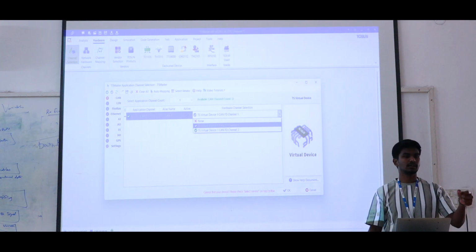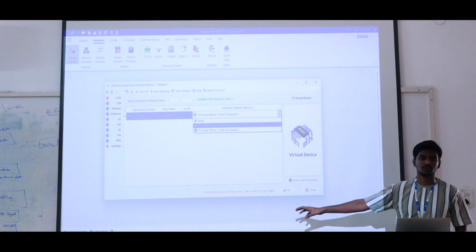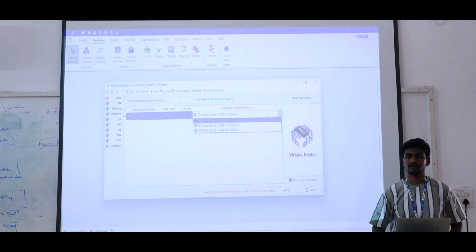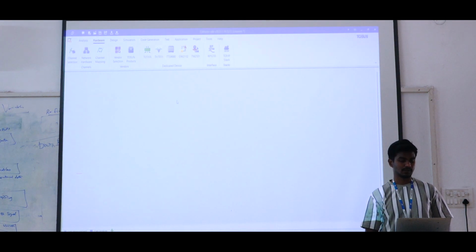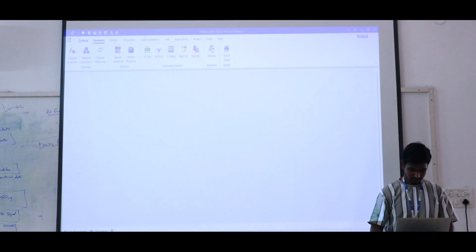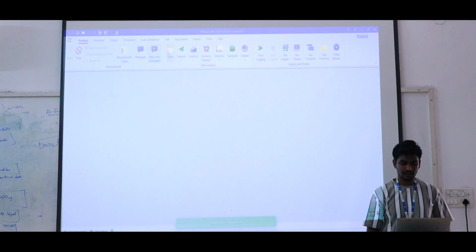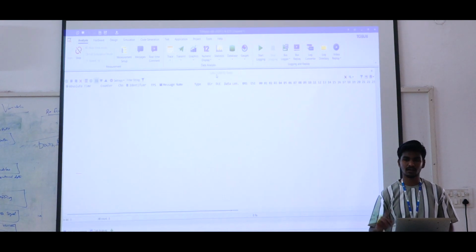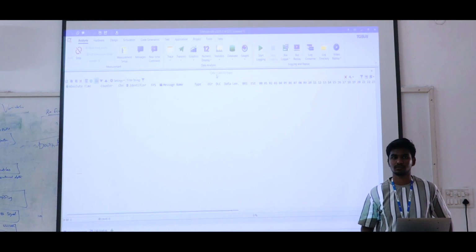Please ensure that your kit has power supply. Turn on the power supply and then connect the peak USB to your system port. You just connect the peak USB. After that, set the channel mapping. Go to analysis and then turn on the simulation. You will get the trace window with two IDs, which means one is RKE, one is the body control module. Two IDs you are able to receive as per our yesterday's code. Yes?